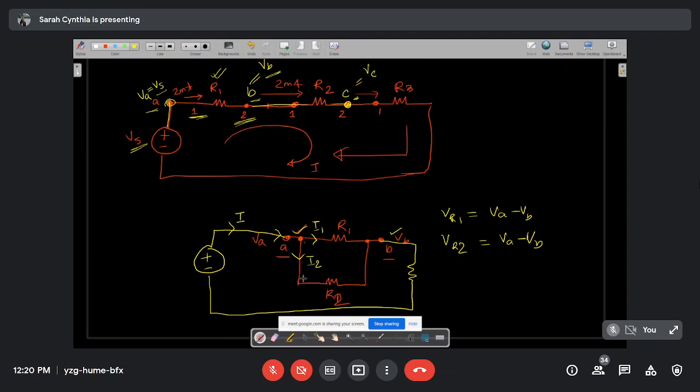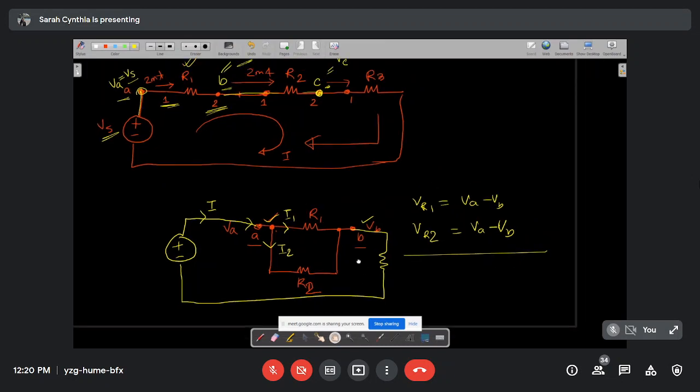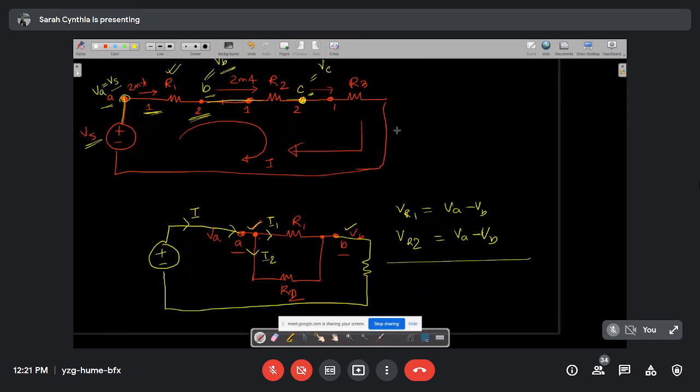This is the characteristic of a parallel circuit. The voltage drop will remain the same, however the current will be divided, or split into two. In a series circuit, we have said that it is a voltage divider circuit. The voltage gets divided across each of the components. However, in the case of parallel circuits, it is a current divider circuit. It can be called a current divider circuit. Do we all understand?